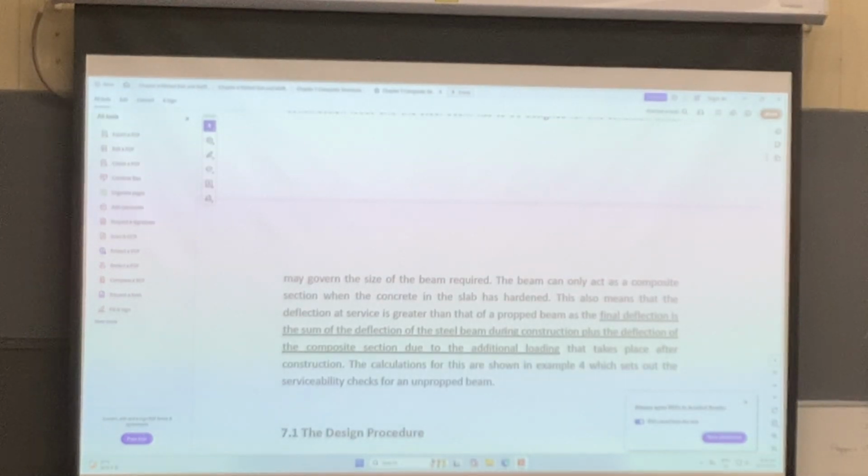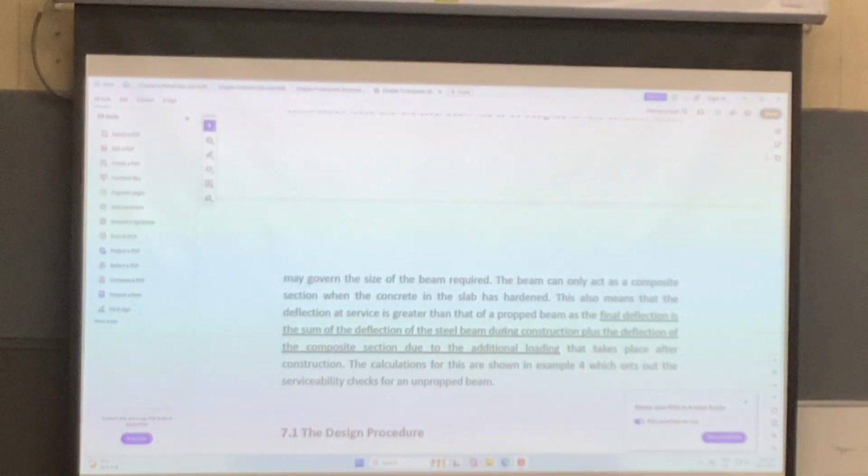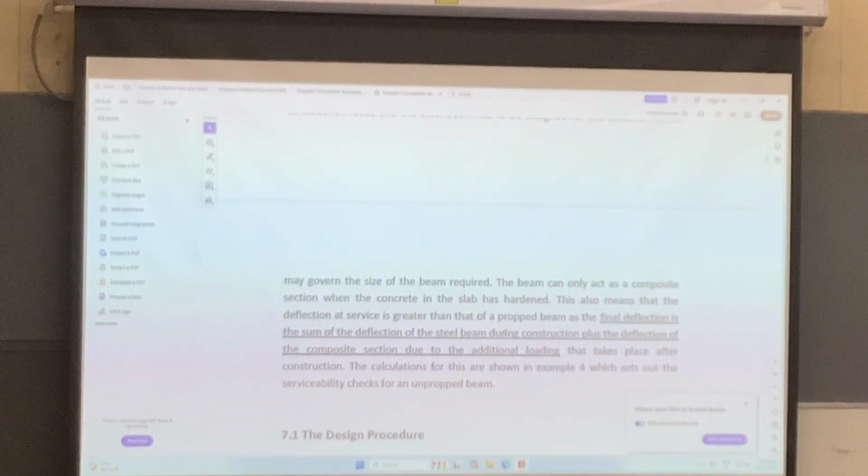So there is no loading stress here, but here there's loading stress, and then due to the composite stage, concrete and the steel beam work together, so this is that one here. Okay, this is the composite stage, this is the loading stress. So the overall stress is the loading stage plus the composite stage. Okay, so this is the steel beam, and then this is the concrete.